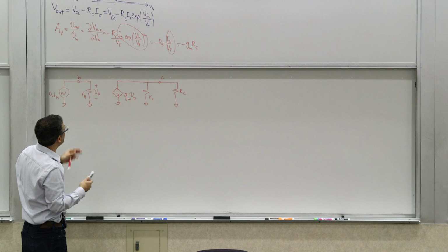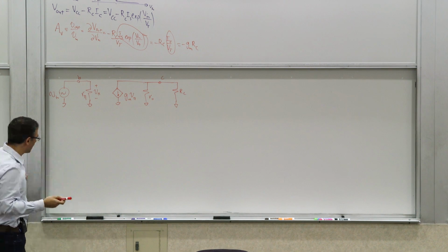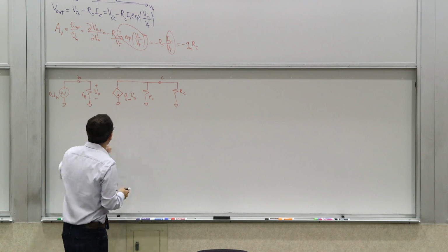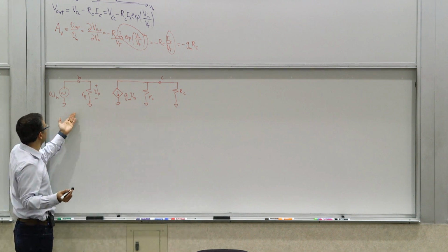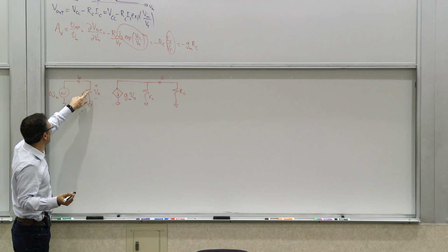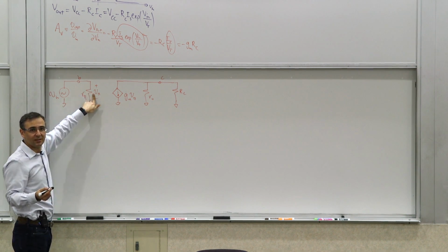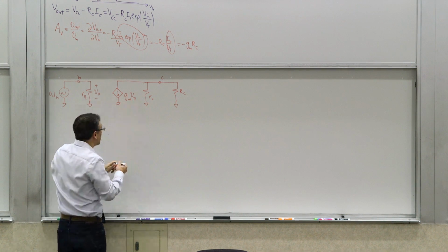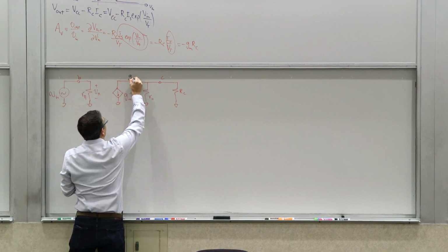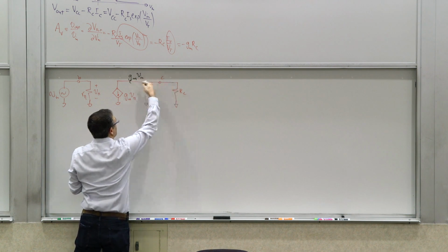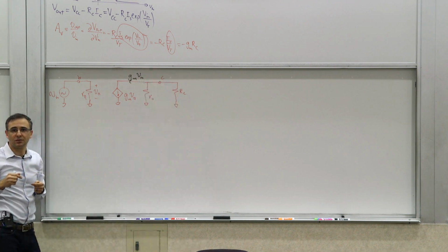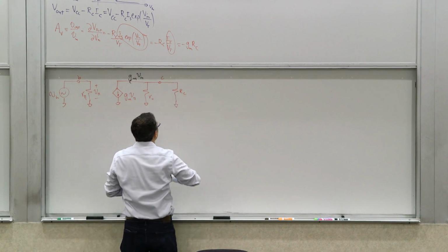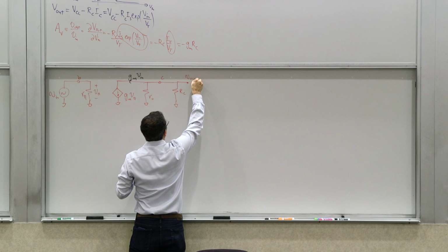Okay, so that's the equivalent model, the pi model. Many of you have already seen this model. And then the question is, what is the calculation of the gain? So we can do that, right? So if this is Vin, V pi is going to be Vin, obviously. It's the same voltage. So this is going to be gm Vin. So you have a current of gm Vin being pulled out of this parallel combination of these two resistors. So what is this voltage going to be, which is Vout, really?